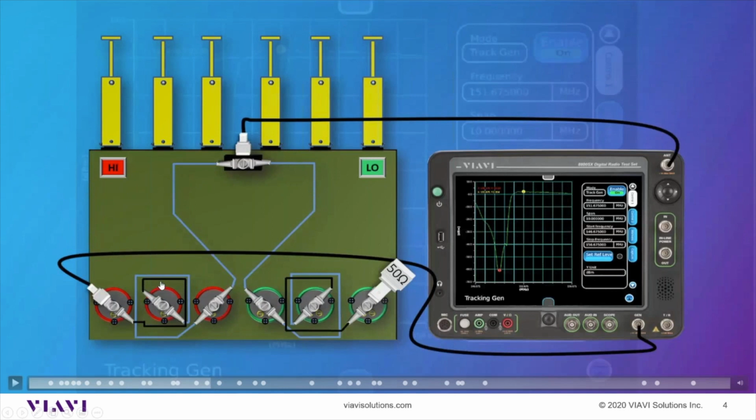The cables that these lines represent are actually part of the frequency response of the duplexer. So when you put these cables back on, it's going to shift your frequencies a little bit, and you're going to have to tweak all of those back in. We'll be operating our plungers, and we'll be using our tuning caps to do that.